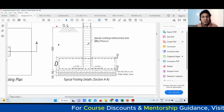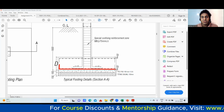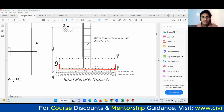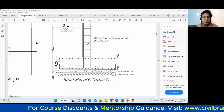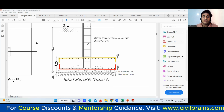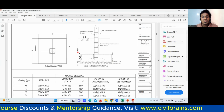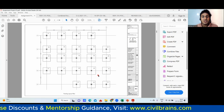If you observe clearly, the bottom reinforcement is given, which we usually give in an isolated footing, and then the distribution bar. Similarly, on the top also we have given. This is actually like a case of a combined footing, but it is not a combined footing because you have one footing and one column. I explained the reason behind that.